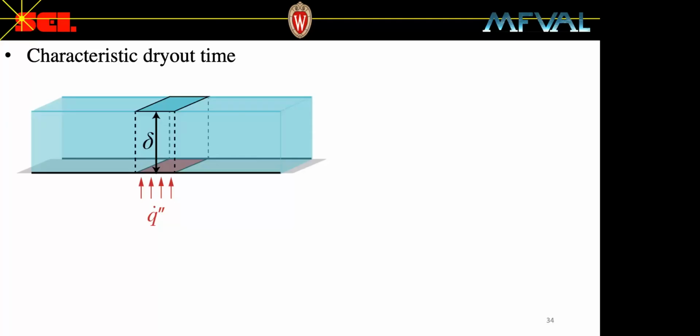Furthermore, through liquid film thickness data, which I don't have time to show you today, it was observed that during intermittent dryout, the liquid film was on the order of 30 to 40 microns, and the viscous sublayer is estimated to be about 25 microns. So any perturbations at the interface could therefore expose the viscous sublayer, the local position to the vapor core. The increased contribution from the viscous forces near the wall would dampen the propagation of surface ripples, causing the liquid film to become very, very smooth, which we observed in the video.